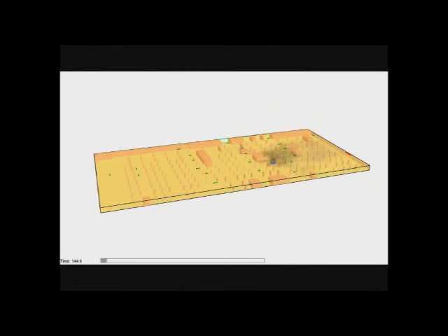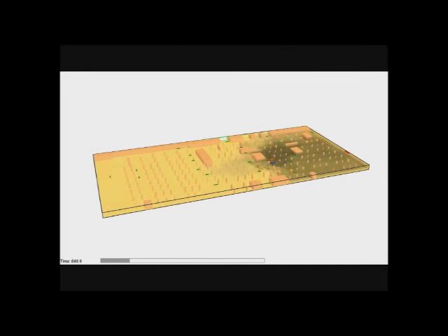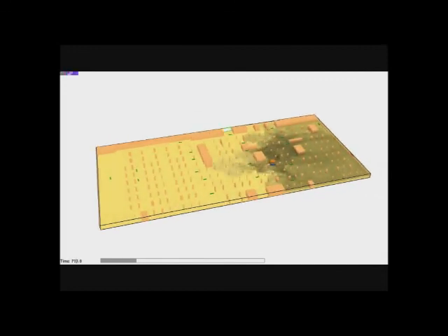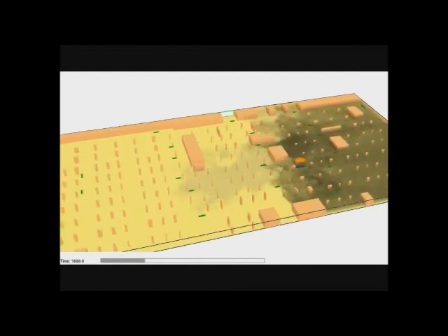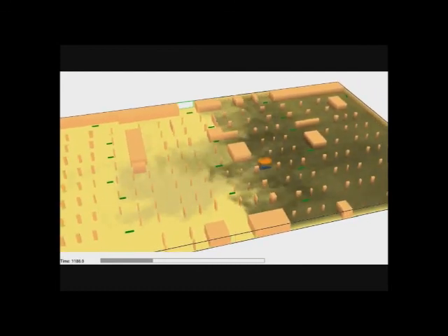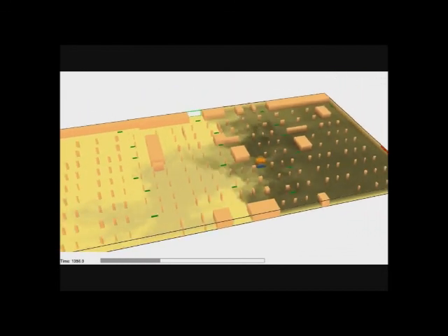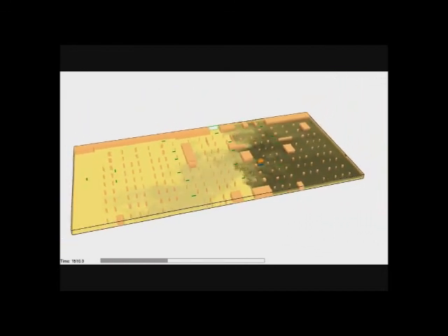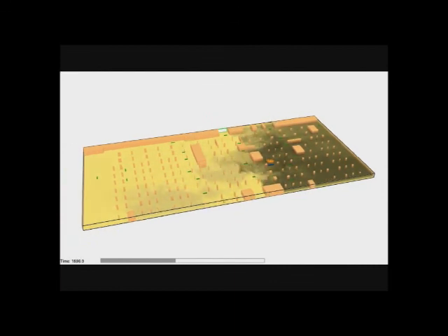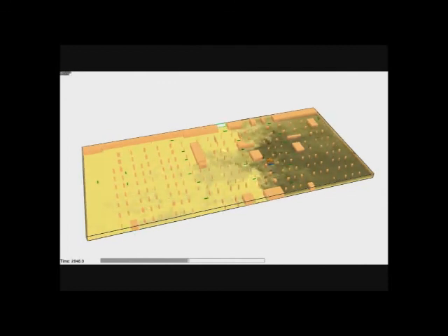Here you see very good compartmentalization, with zones defined in this car parking area using these jet fans. These jet fans are able to keep the fire and smoke constrained to this zone only. There is not much smoke going elsewhere, and it is very light smoke, so it doesn't matter because visibility is good in this complete area. So the whole of the smoke is mostly constrained. This is also a reasonably large fire. 3.1 megawatts is the fire intensity, which is standard, also specified in standards.